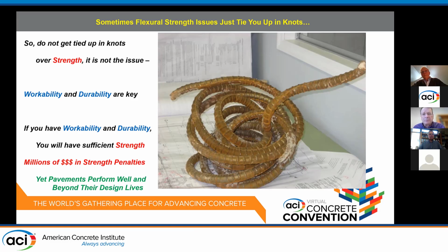Well, I think the comment I made at the end was, let's look at getting rid of the flexural strength beam test. We can do those things in the lab, establish the mixes, come up with the maturity relationships, and then let's control the concrete for payment and acceptance in the field with maturity. We can get results quicker than 28 days and quit messing with a test that has a tremendous range of variability. That would just be my thought.